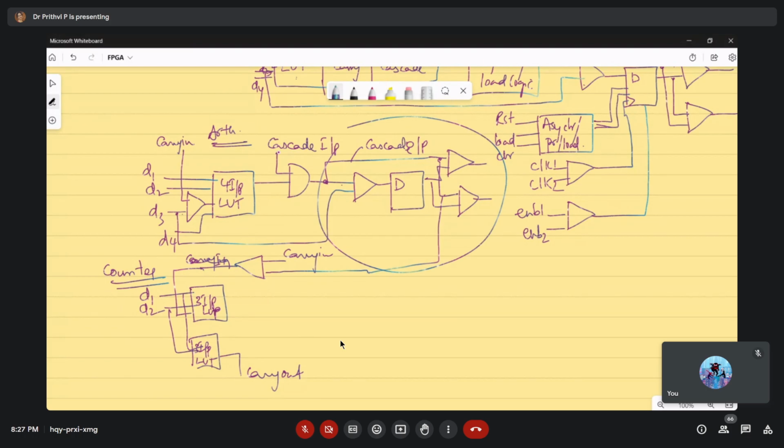So the same logic element, you are able to configure for different operations, different functions. You are redefining the internal connectivities. What are these interconnection networks we are having? An SRAM based FPGA uses the SRAM to hold the information of the program of the interconnect. So it can be reconfigured within the logic element. But this interconnect point, which we normally call the connection box, all the points are what I have shown here in the previous thing.